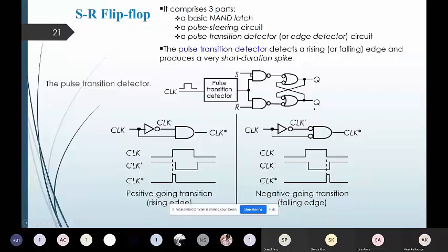We know that when both the inputs of the NAND gate are 1, we are going to obtain the zero output. And with this principle, if I find this S value as 1 and the positive edge trigger is happening, the upper NAND gate output will be 0. But when this lower R input is 1 along with the positive clock, then the lower NAND gate will produce the output as 0.